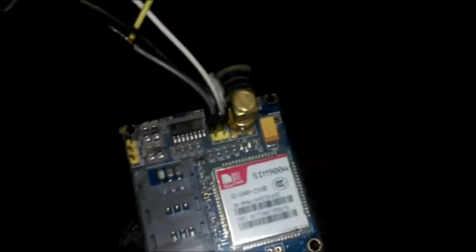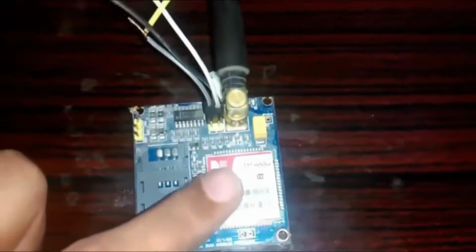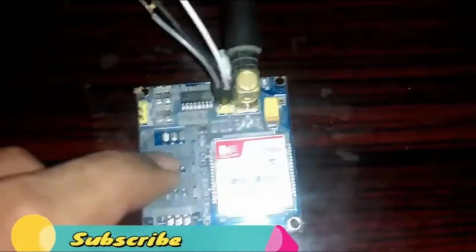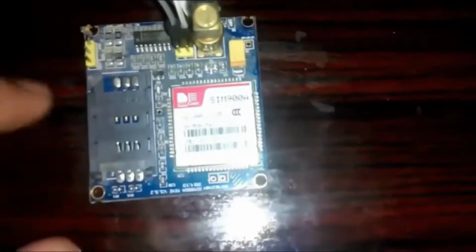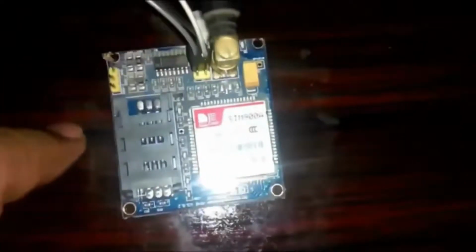So let's start. If you are from Pakistan or India, first of all make sure that you purchase the unlocked version of the SIM900A. If you're using SIM900D, then you'll have no such problems. When you purchase the SIM900A module, you should ask whether this particular module is locked or unlocked, so that you don't purchase the wrong version. If you purchase the wrong version, it will be blocked automatically.